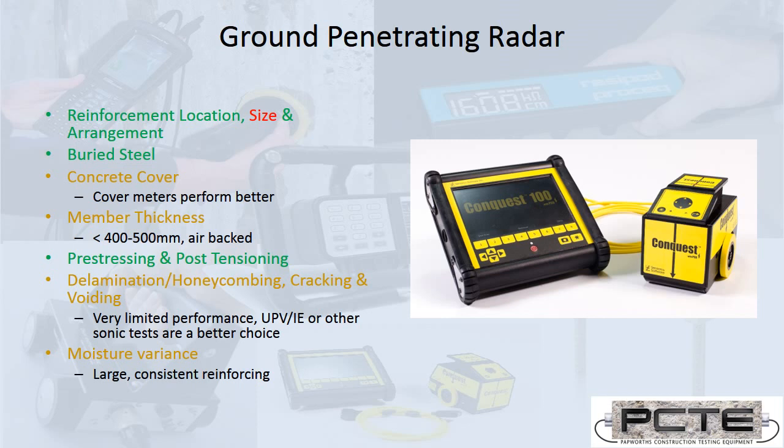Finally, moisture variance is mentioned as well. This does work, but again, in two ways. If you have very moist environments close by to very dry environments, there will be a marked contrast between the two. It's also possible to measure on a known geometry a radar signal transmission speed and compare that. But this isn't something that you can do just by a scanning method. It's a more involved approach done by a more skilled GPR operator.